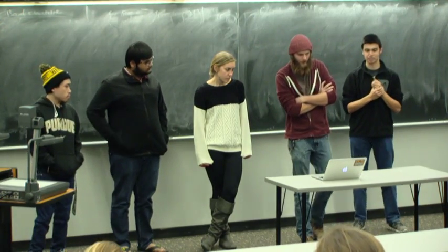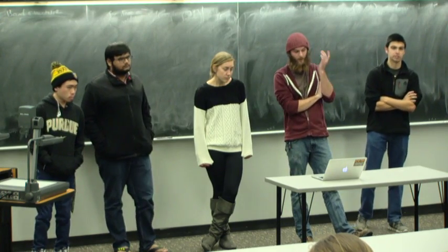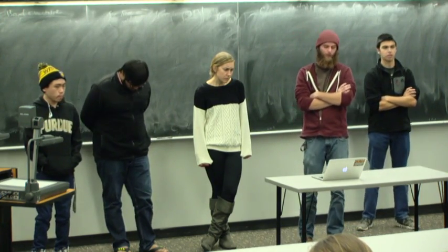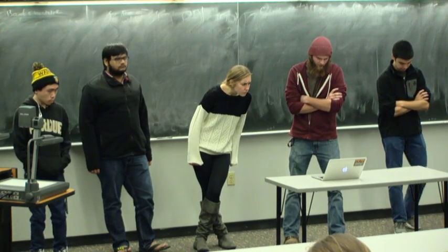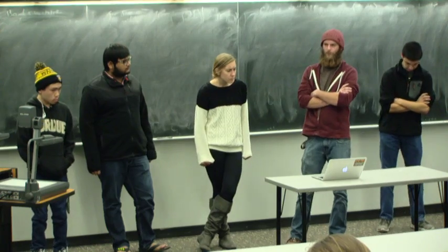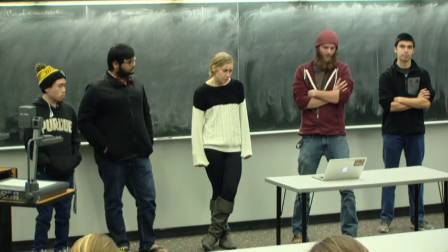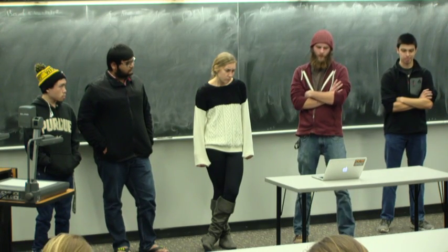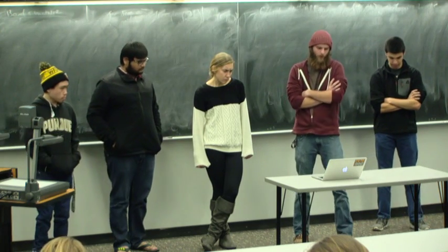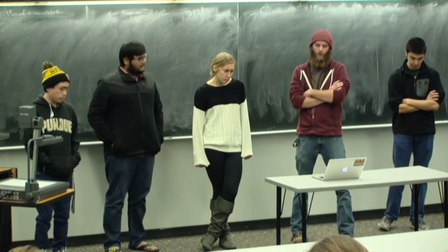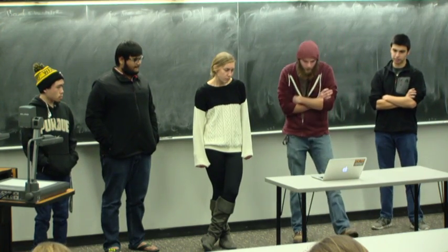Alright, we also put down audio quality as a process function, and the potential failure mode for this is you can't hear them or it's non-comprehensible. This would be frustrating to use. We gave this a severity level of 8 just because you should be able to communicate when you're using a webcam. The potential cause for this may be a bad microphone. We put an occurrence of this also at 4 for the same reason. Current process controls also use high quality materials. The detection of this would be about 2, with an RPN of about 64.